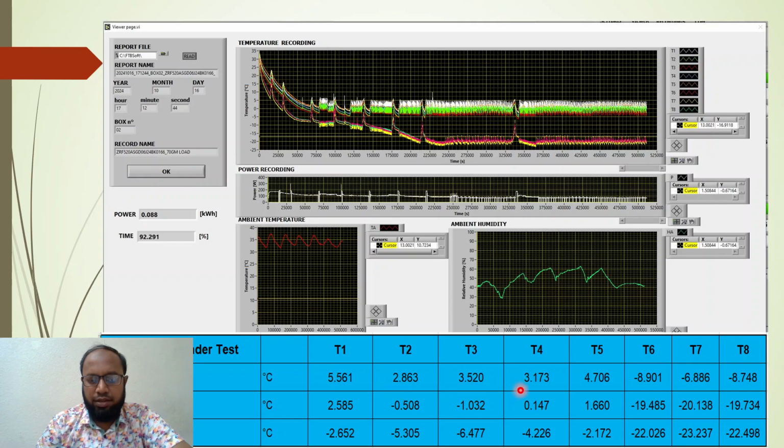Here we get the maximum average temperature data, and here the average with respect to minimum temperature data of the refrigerator chamber, and this is the freezer chamber temperature data. As a result, after fixing the refrigerator performance data, we analyze the refrigerator with respect to load, temperature data and energy.